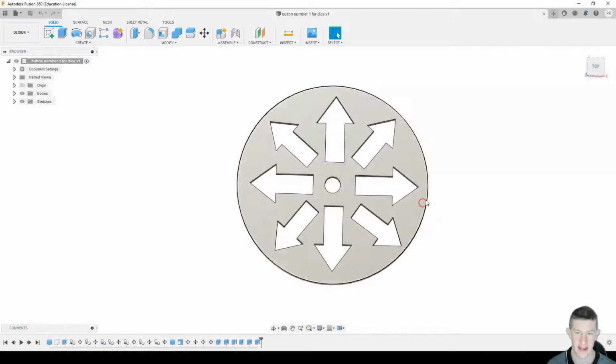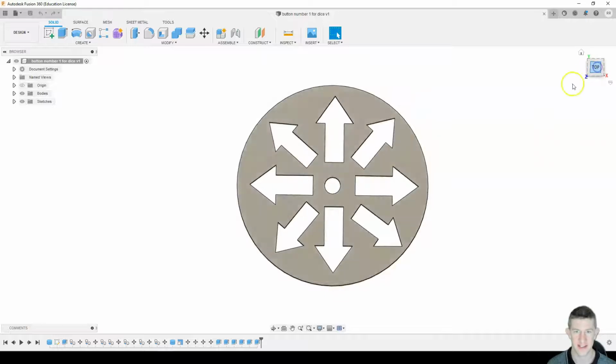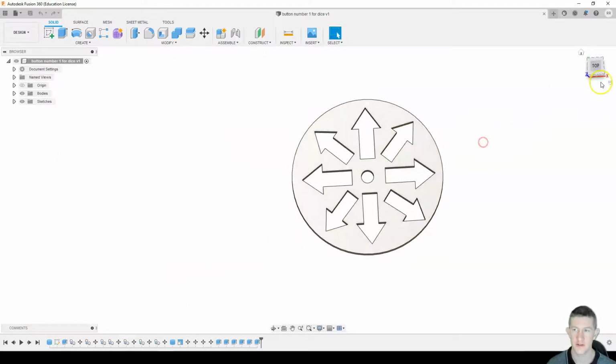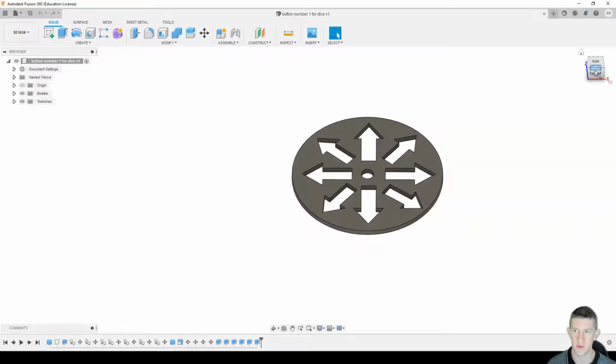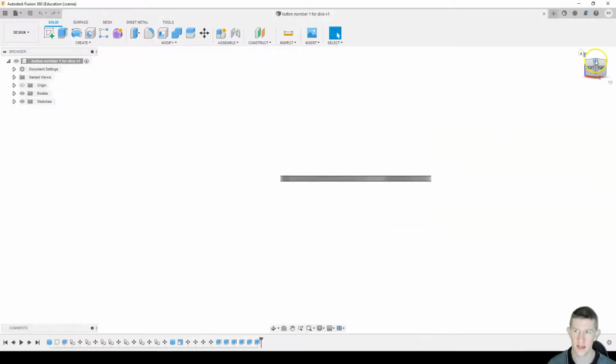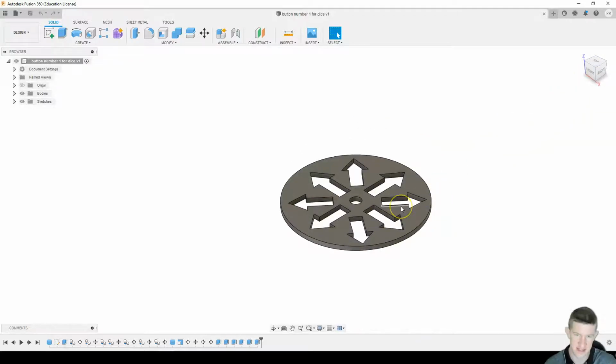Sometimes if you're on a slight angle like this, it looks flat and I'm drawing, but when I actually snap it, it wasn't quite flat. So it's really good to use. You can also use that to snap to things like a vertex. If I angle it a bit more, I can snap to a corner and be on a perfect 45. I can do another corner. I can do a top corner. So I'm looking down at a 45 in that, and things like that.